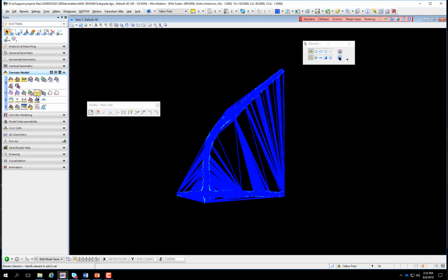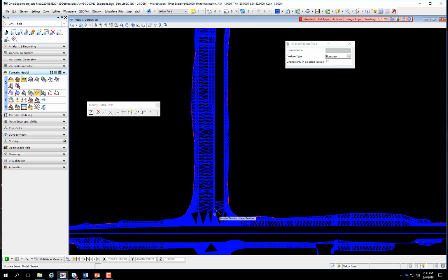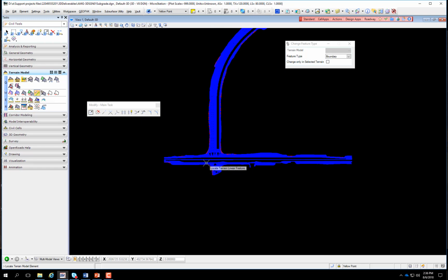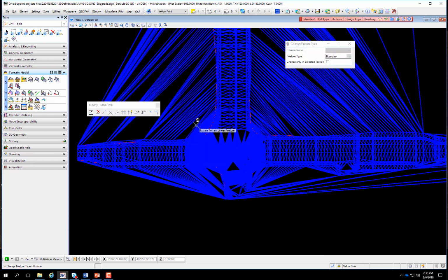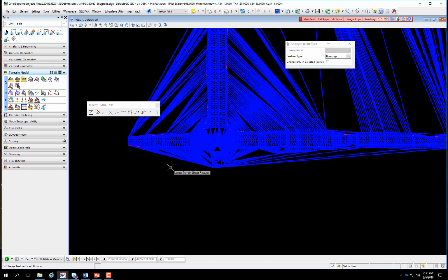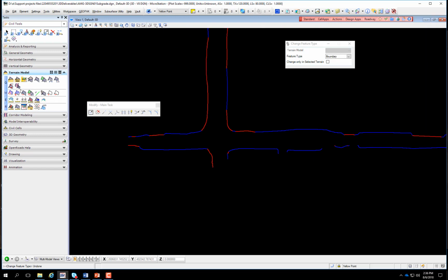And then I'll use this tool, and it says there's 34 cut fill elements, and I want to use them as a boundary on this terrain. It already knows that they belong to this terrain. So if I just go ahead and data point and select the boundary, you'll see what happens is the way it's trying to form the boundaries, it's not working properly. So I'm going to do a Control Z and take those boundary elements away, and then go back to my levels and turn off these triangles, and then I'm going to select them.